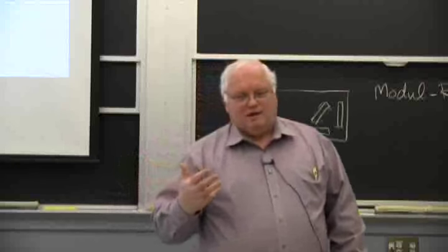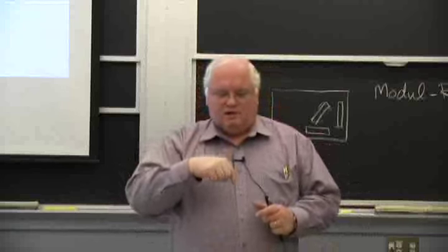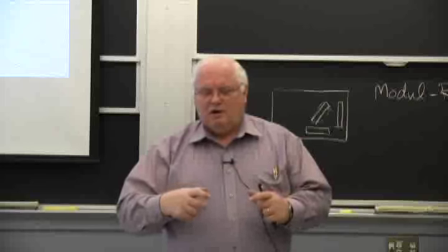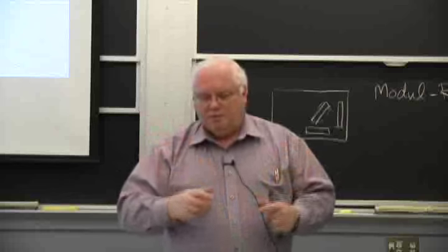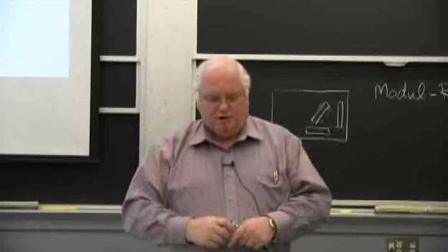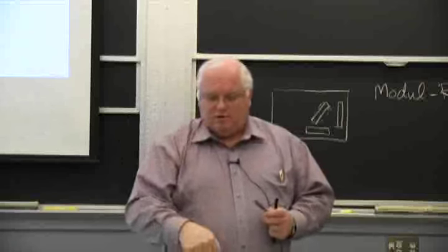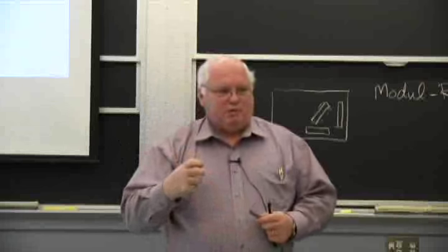Okay? And so you can have an electron beam that gives you your power, and then the signal you want to put in there, which is for phased array radar, will basically amplify that little signal, and the electron beam gives you a big signal. But on the end of these little copper fingers, when you're pulsing that electron beam, it generates so much heat that it would melt the tips of the copper.